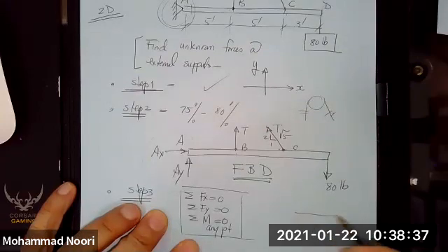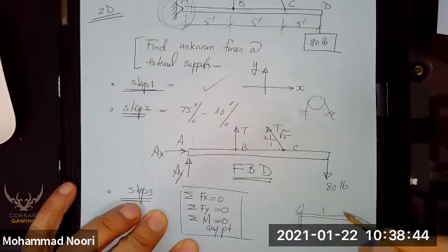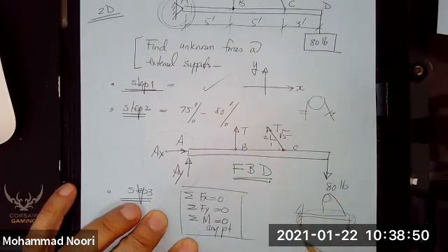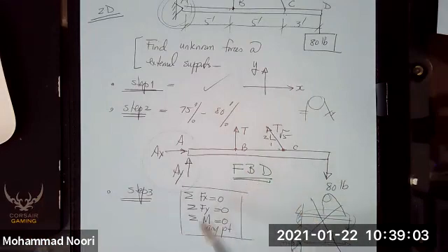What do I mean by that? If you had this object like this, fixed support here, then you had these 2 cables going around this, right? You drew the free body diagram of this object. You have this, this, this, and these. So you have 4 unknowns. You cannot solve this problem. When you have more than 3 unknowns, we call that problem statically indeterminate. That means your knowledge of statics cannot be used to solve that problem. It doesn't mean that that problem cannot be solved. Your knowledge, which is limited to static equilibrium, cannot be used to solve that problem.